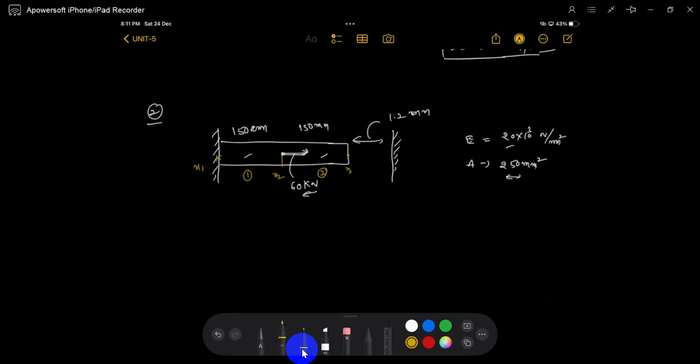Now we can observe it. If the displacement of the member exceeds 1.2 mm, it will experience a force. Otherwise, if the displacement of the member is less than 1.2 mm, there is no stress. Understood? If the displacement in the member comes to this much, there is no extra repulsive force because there is no touching. Otherwise, there is no restraint of the displacements.